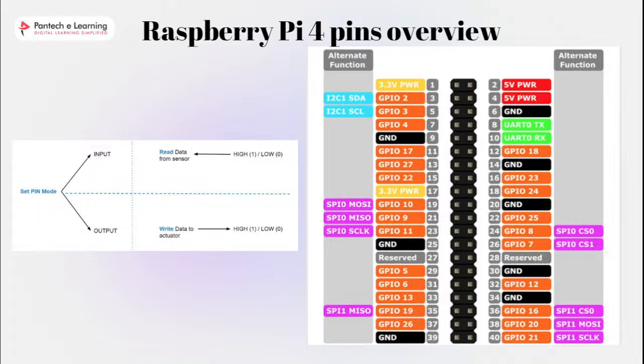If you add a new sensor or an actuator to an existing circuit, connect the ground of the component to the ground of the circuit. This is the main thing, and it's very important. Without that, you may burn some parts of the circuit, you may have components that don't function correctly, or maybe it will give you wrong values also. So you have to make sure of the ground part, right?